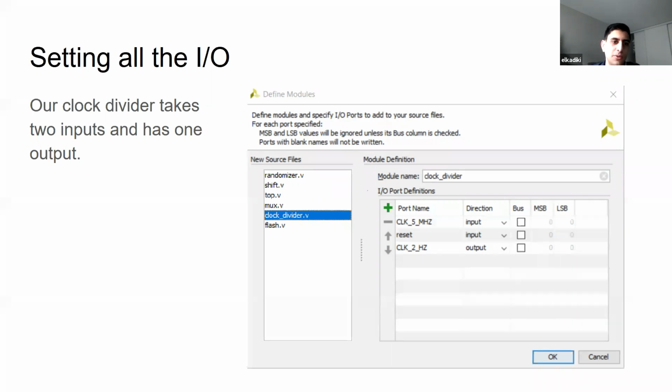Well, I guess you can always assign it to a switch. Tick, tick, tick. I think one of the labs forces you to do that. And Vivado doesn't like it, right? Because you're saying treat this switch like a clock. It's a big no-no, apparently.